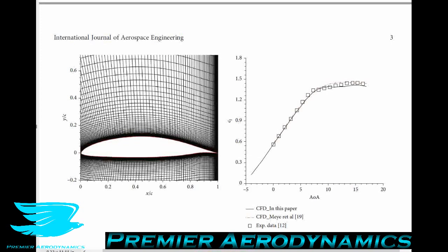Now, even at Mach 0.3, the flow is still being compressed by about 2%, the density is increasing by that much, and that's still quite a decent error, but that's just the rule of thumb that has come down to us over the years. If you go to Mach 0.2, I think the density changes are not even 1%, so that's even better. But that's just the rule of thumb we use. So a Mach number of 0.1 is quite good. It means that we have almost no change in the density.